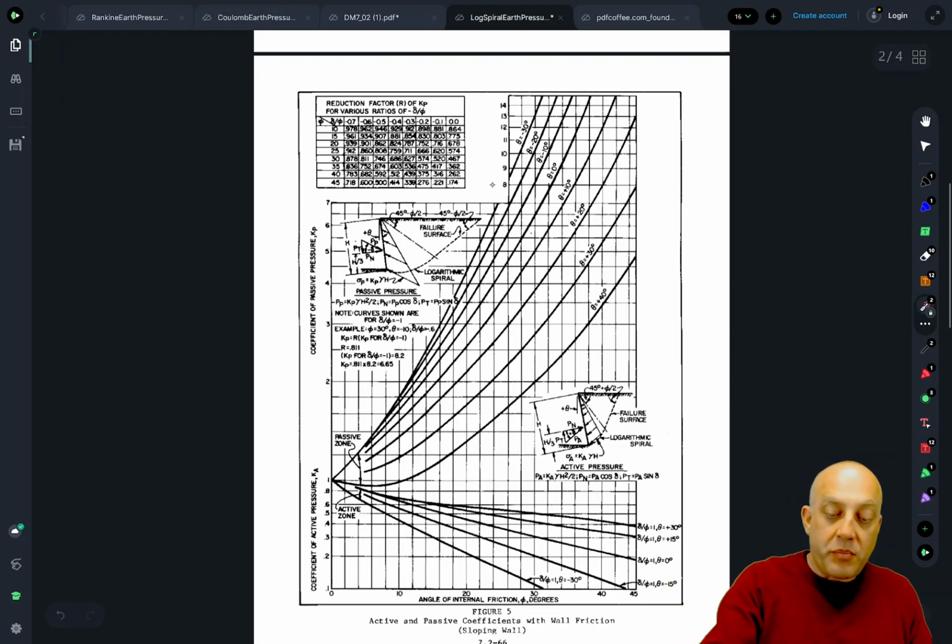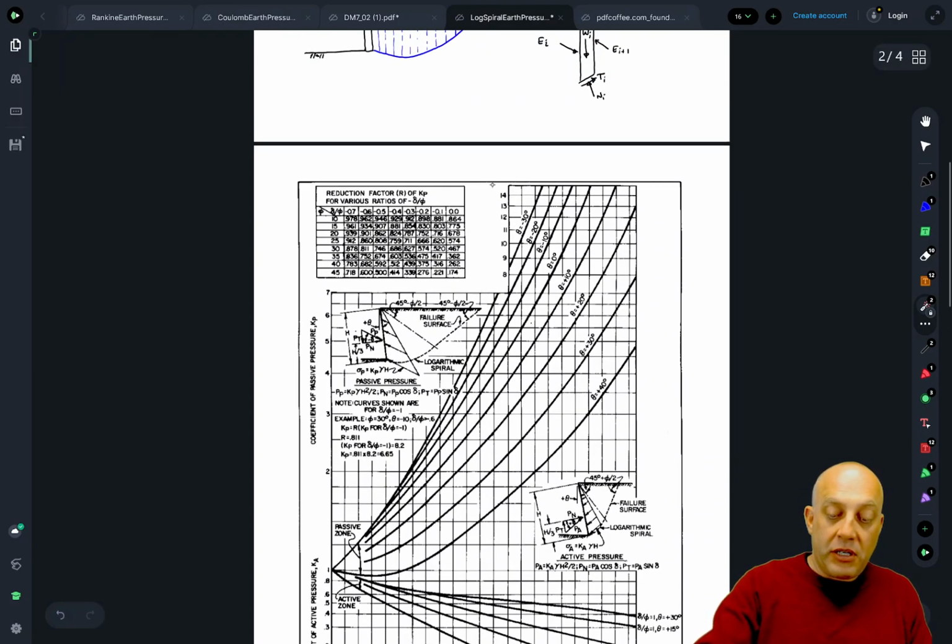This table has passive earth pressures kind of above this 1.0 line, and active earth pressures down here below the 1.0 line. So it's a fully formed table where you can do both passive and active pressures. You can check this, but if you come out here to some typical friction angle, 30-something degrees, you're going to get a result that's very similar to the planar rupture surface if you do the active coefficients. What we're going to use this for primarily are the lines up here. These are the passive lines.